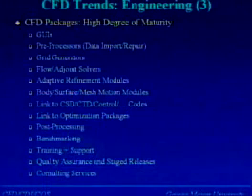Now, all of these CFD packages have a very high degree of maturity. They have very nice GUIs, very nice preprocessors, grid generators. They not only solve the flow field, but the adjoint, which is very useful to determine errors, to know where to refine, if you're doing optimal shape design, things of that nature. They all have adaptive refinement modules. They can move bodies or attach to CSD code, link to optimization packages, and so on and so forth.